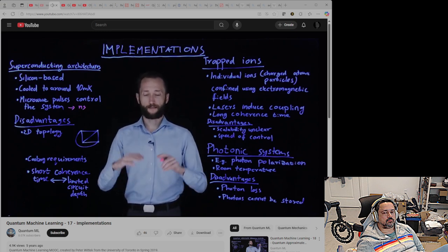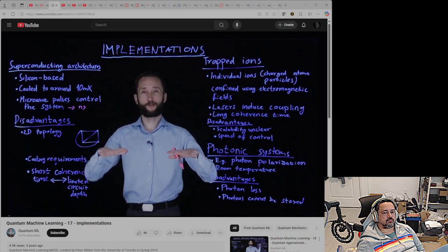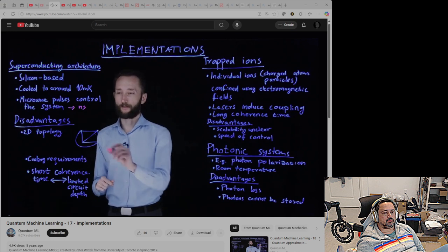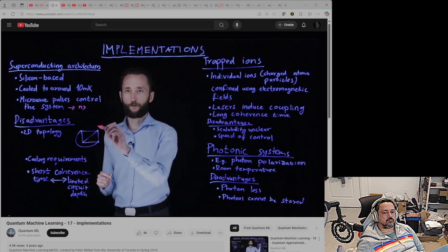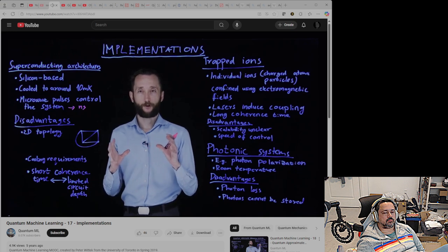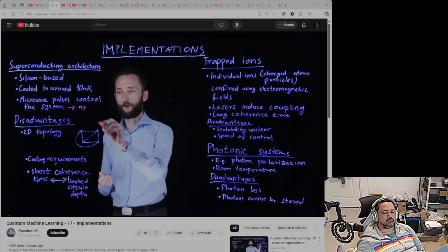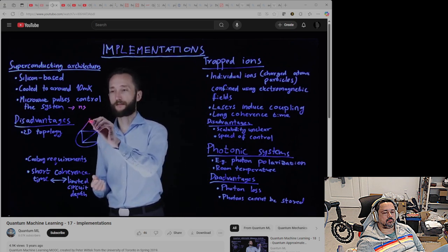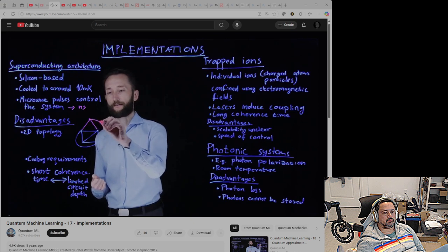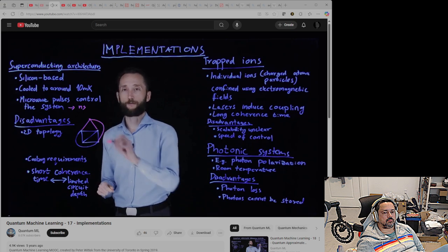First of all, since you have this silicon wafer, this is fundamentally two-dimensional. So imagine now that you have 4 qubits implemented, then you can have full connectivity between every pair of qubits. So you can apply gates between any pair of qubits. But the moment you add a 5th one, that goes away, because there's no way to connect this 5th one with all of the other ones. You cannot cross the wires.